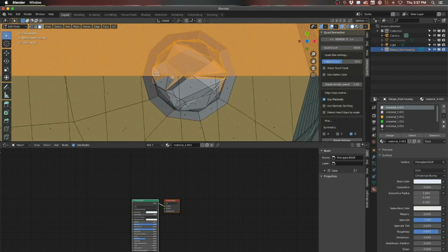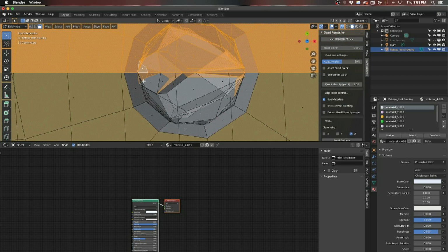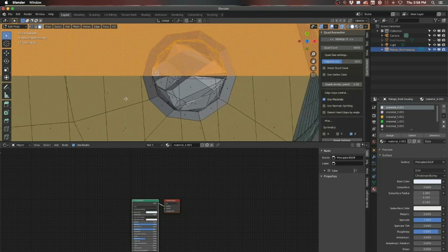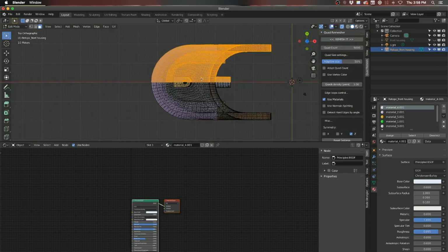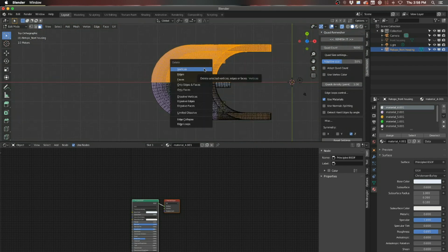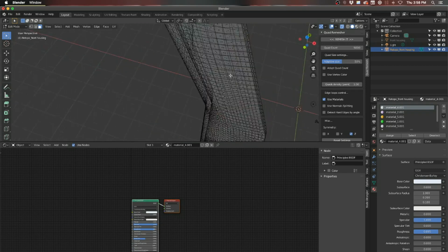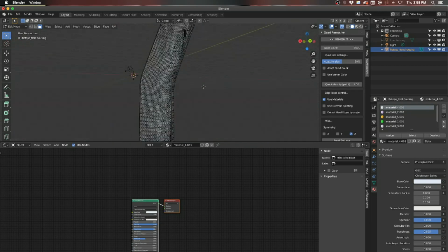There's some funkiness, and I can actually press C and then Shift and deselect anything kind of as a selection paintbrush, and then right click, and it gets me out of that mode. And I'm going to hit X to delete them and delete these faces. So now we have half of the model.